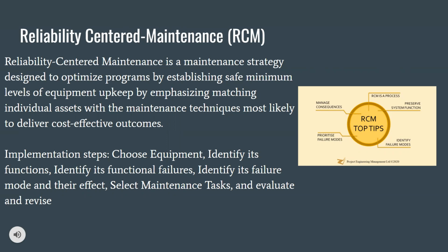We would choose the equipment, identify its functions, its functional failures, its failure modes, and their effects. And then we will select maintenance tasks and then just evaluate and revise until you're satisfied. Now, this method gives us many benefits, like setting realistic expectations, providing more insight on risks, and managing those risks, and just overall cost reduction.